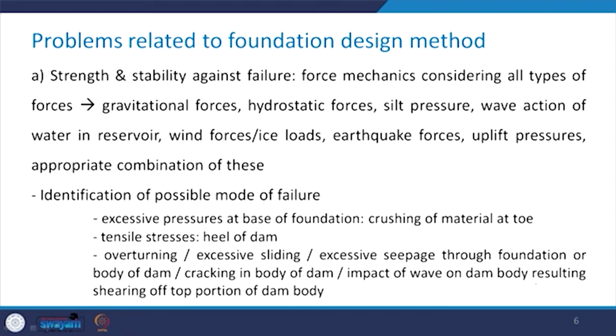These can be gravitational forces, hydrostatic forces, silt pressure, wave action of the water in the reservoir, wind forces or ice loads, earthquake forces and uplift pressures. Plus, there can be the appropriate combination of these forces which can act on the dam, foundation and abutment system.